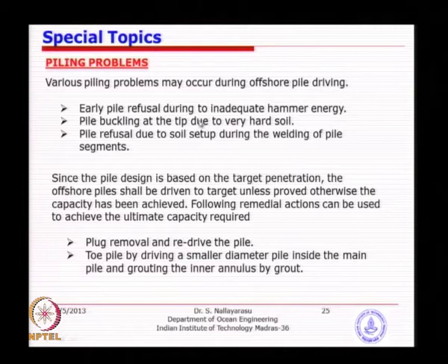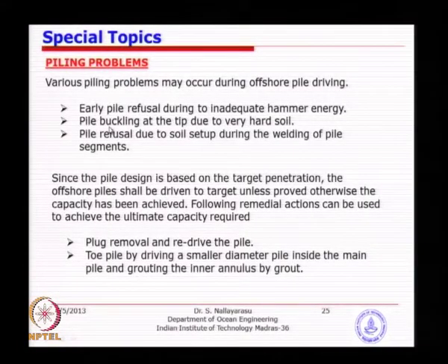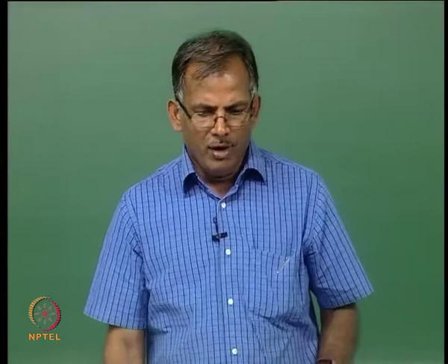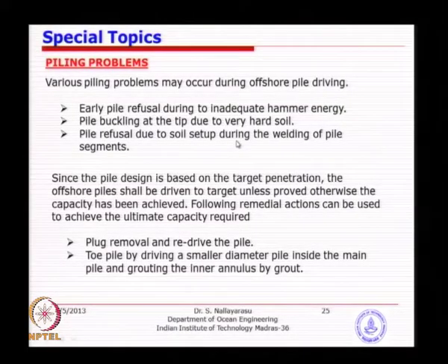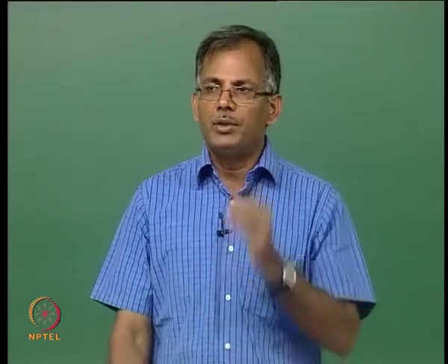So what can actually happen when you have an early refusal, because your theoretical calculation of pile drivability is not correct or misunderstood, or the soil is actually stronger than your understanding, because your borehole is incorrectly understood? There could be pile refusal even after doing so much engineering work. Pile buckling, because your calculation of pile stresses was incorrect, so the pile starts to buckle locally because there is a big boulder. Pile refusal due to soil setup: your hammer breaks down or weather conditions do not permit you to drive continuously, you stop, and when you go back to start driving after, say, 2 days, you see that the resistance is larger. So these are some of the areas where unexpected things can happen, so you need to get prepared for it.